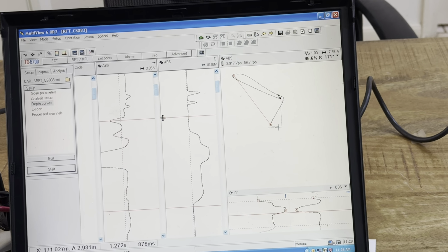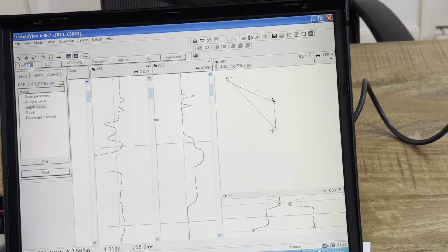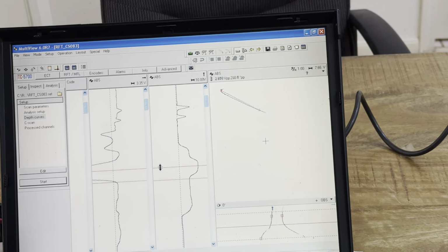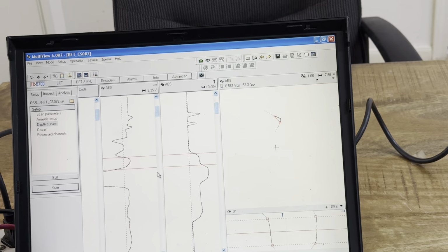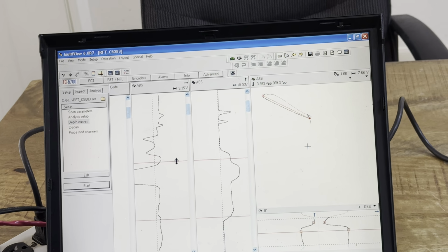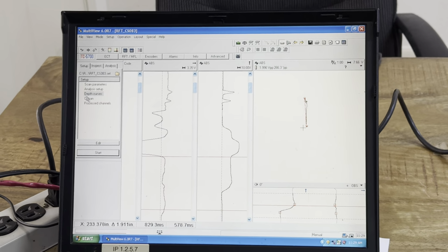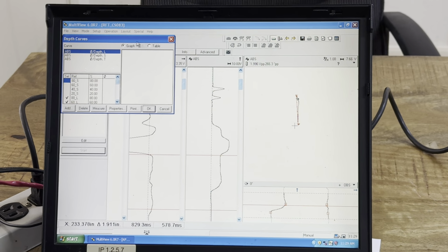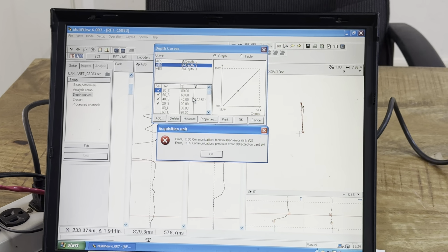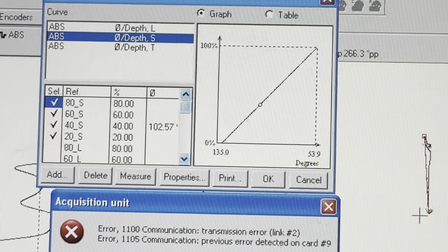So if you want to see all of that, you can see the support plate and the signals. The support is here, support here again, the first coil, and then the second coil, and then back to the 0 point. Overall, it will look like this. Here we go. Then we have the depth curves. We make a depth curve which will look like this, and they will be something like that. We use the depth curve, and if we see any flaws, we use it to estimate the depth of the flaw.